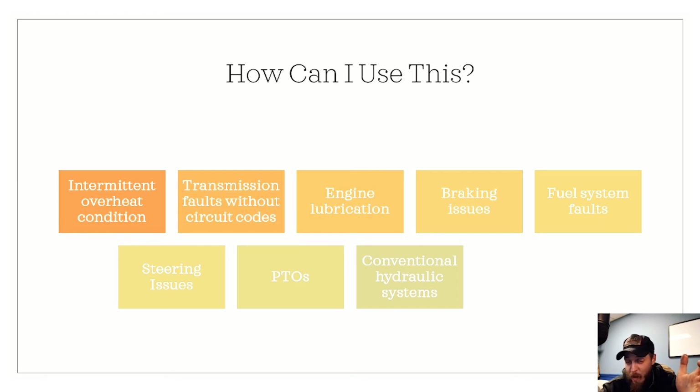basically Pascal's Law allows a very, very small machine to do some very, very big work, not factoring in leverage with longer dipper arms and everything else, but you can do a lot with a very basic equation. Force is equal to pressure times area. It's pretty cool, at least to me.